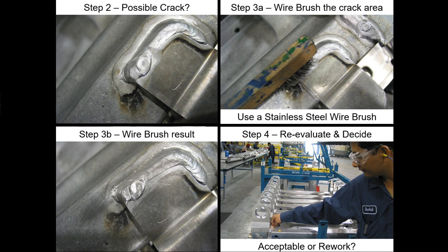My point is, from all this, take an interest in this. Take an interest in your station, at least for a while. I know it becomes mundane, and I take my hat off to the people that can do reprocess like this. It's challenging. But take a moment to understand your station. Understand what you're fixing. You will understand your responsibilities for fixing, but how many you're fixing. Watch when there's consistent problems, right? Don't keep making bad parts all night and welding just because you like to weld or just because you think it's okay. Make sure you alert people to certain situations, especially with aluminum, and especially if you're new at it.